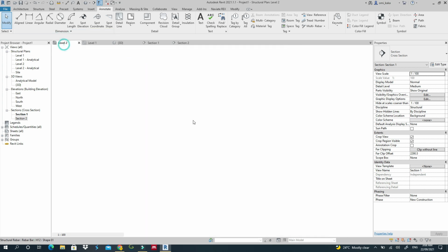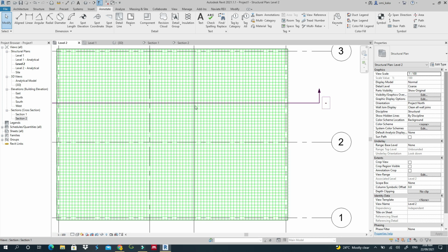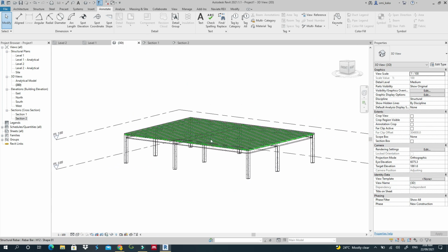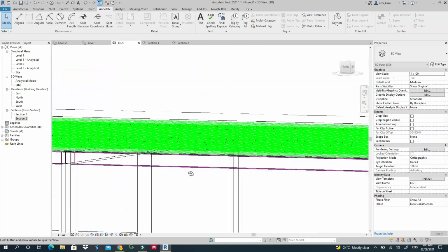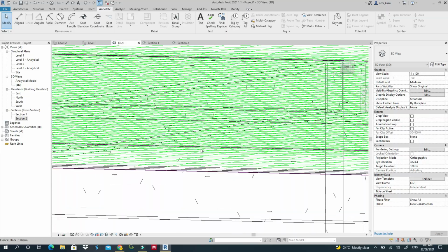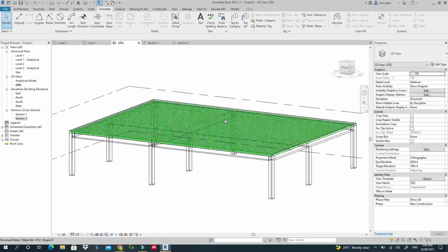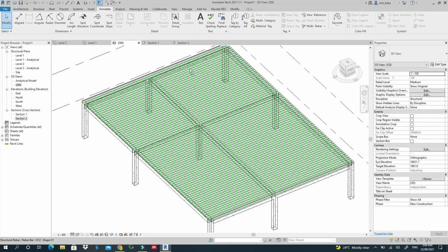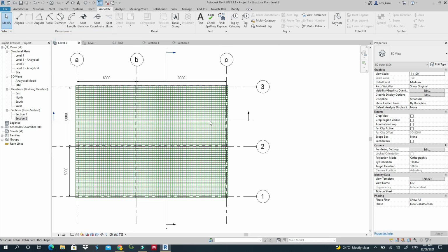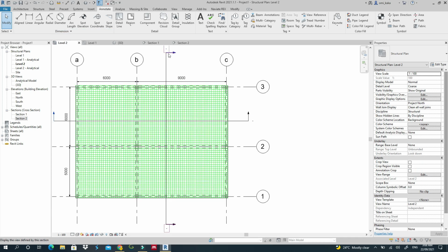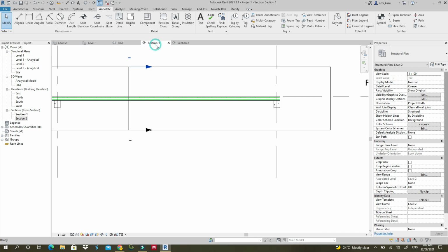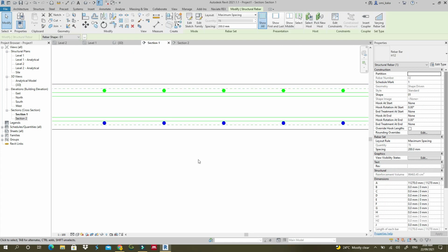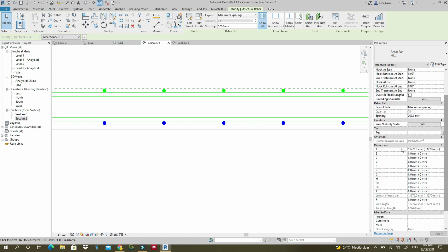And so right now we have bottom reinforcement and we also have top reinforcement. This is the 3D we can see here, I believe. Okay, so what we want to do now is let's name our bars first a little bit. So what I'm going to do, I'll go to section, this one. So this was bottom 1, right? I'll select it and I'll come here.